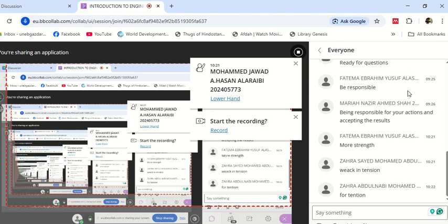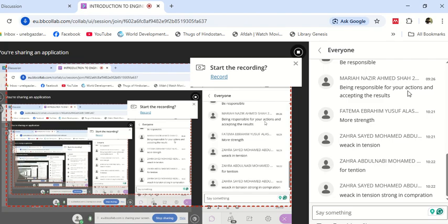Doctor, because of the cracking that may occur in the concrete, since there is some tensile tension that comes to the concrete, and the concrete does not carry any tensile tension. So we put reinforcement with steel, so it carries this type of loads. Yes, so all of you have the basic idea. We are looking for more strength, specifically in tension, because concrete is weak in tension.